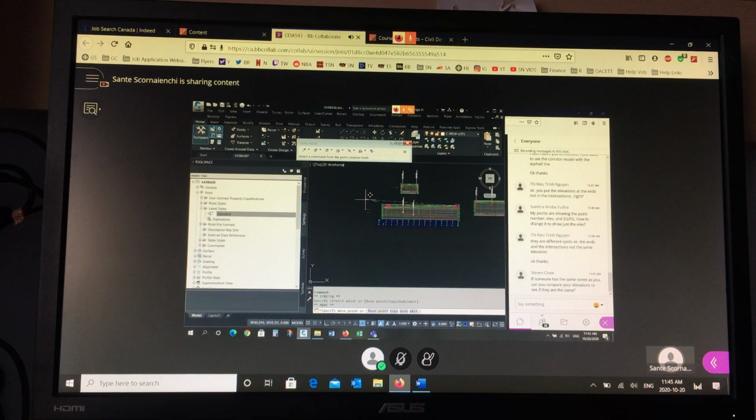I'm going to put a curb and boulevard starting at the original edge of asphalt. So I want it to look like this in the future. And one on the other side. So in the future, this curb and gutter is going to match the edge of asphalt. So that's what it wants to look like eventually. We're going to keep the asphalt in the middle, and we're going to get rid of the shoulder and the ditches, and we're going to have a full section like that.